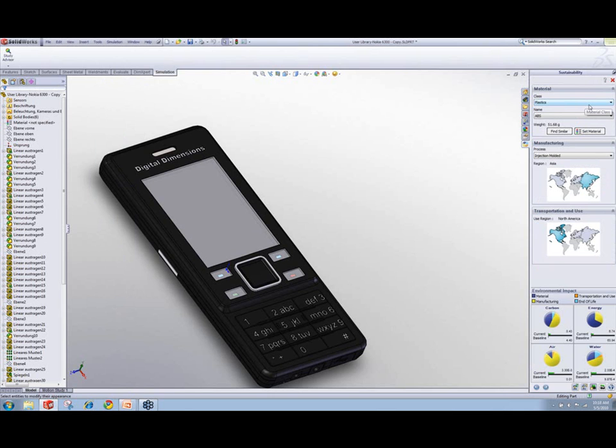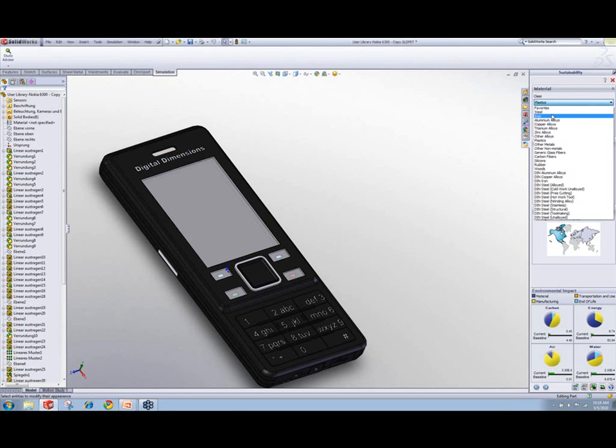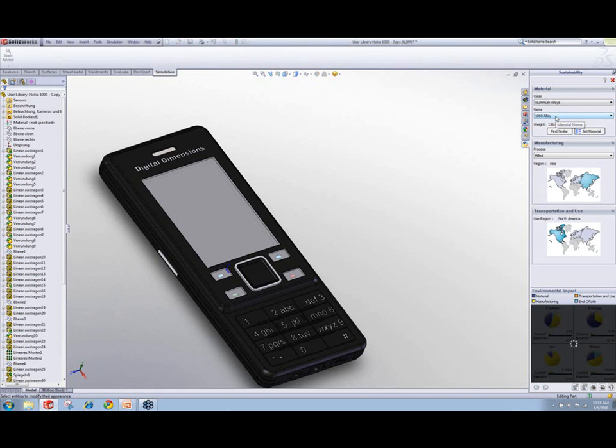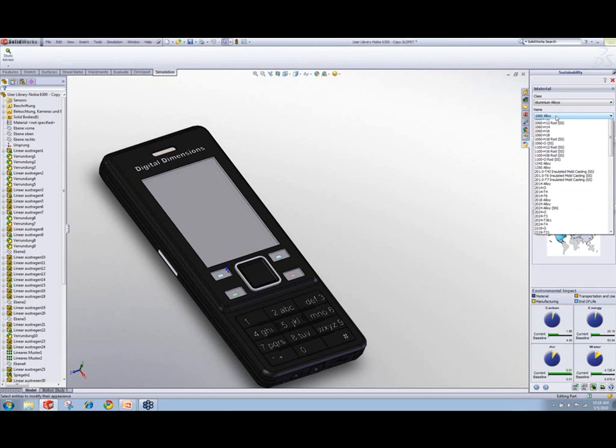Now let's choose an initial material here. Let's choose something nice, something trendy that we see. How about an aluminum? Just to copy the iPhone. Maybe this is something Apple did. And let's choose 1060, it's pretty common. Let's choose that and let's set the material.